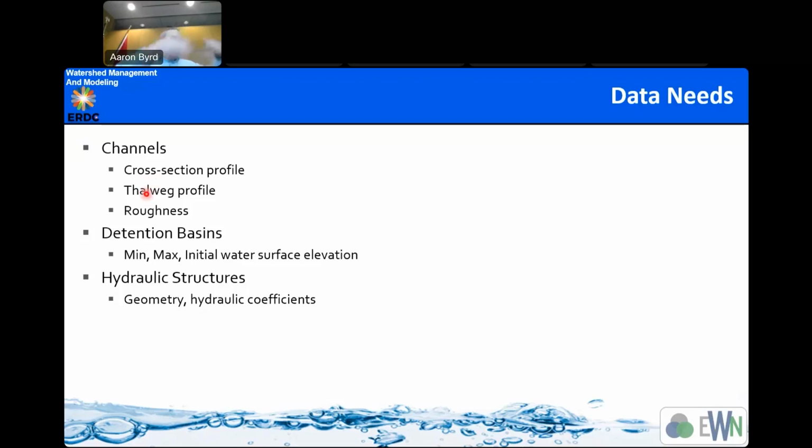Your thalweg profile. This is the vertical profile of your stream bed, the longitudinal profile. Very important. We can usually rough estimate this from the DEM. The DEM will be a bit more jagged than your thalweg profile, but we can over smooth this pretty easily. So you want to figure out where the key breaks in your slope are. And again, this comes back to just driving around.